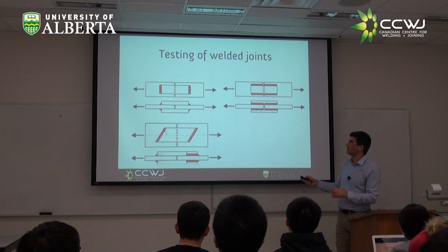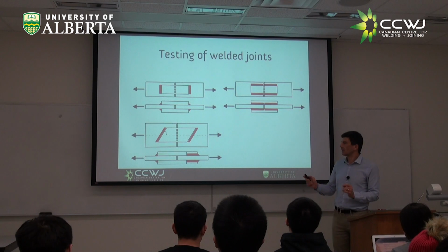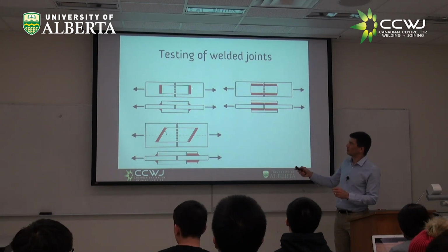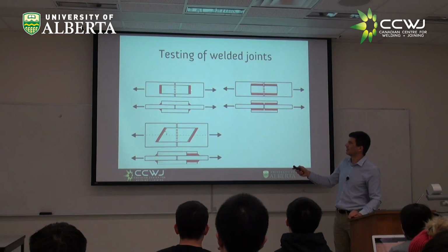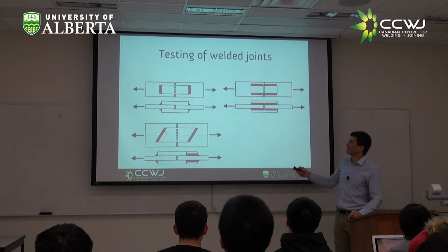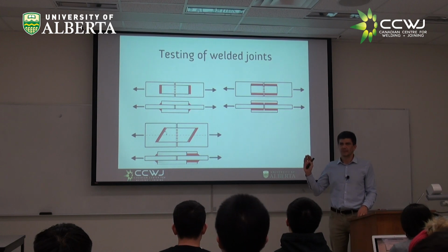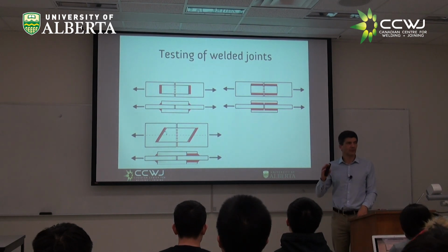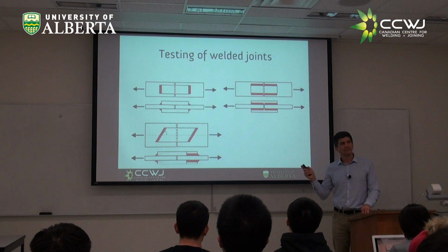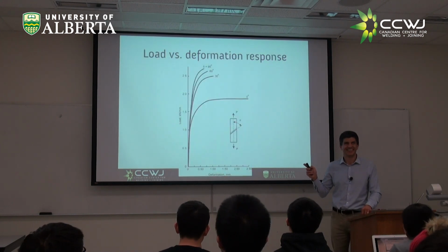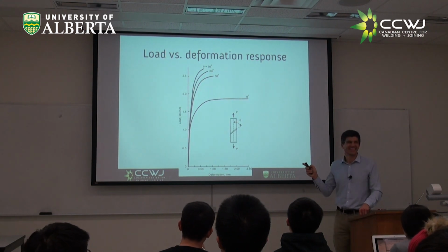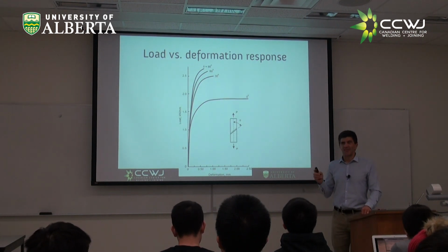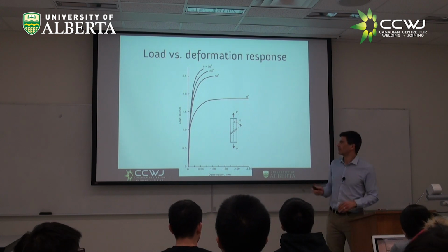We're talking serious stuff. So, okay, do you remember this thing we discussed, right? Fillet welds can be longitudinal or transverse. Do they behave the same? If the same fillet weld with the same electrode and the same procedure, do I have the same strength in this transverse weld as in this longitudinal weld? No. Right? Which is stronger? Transverse, right?